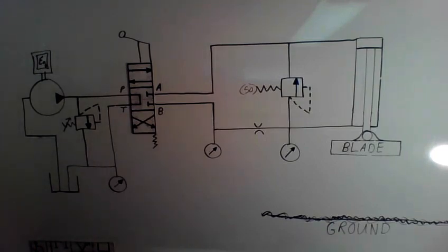Alright, we're going to try and explain the quick drop valve in a practical application for you today. And that is to say there's a valve attached right to the piston end of the cylinder that in the right situation will allow oil to go from the rod straight over to the piston side and increase production. And we're going to increase production by reducing cycle times.